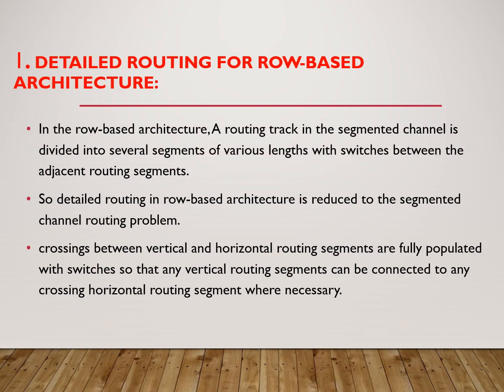Here we are going to see the detailed routing for row-based architecture. Then we are going to see the symmetrical-based architecture. See, in the row-based architecture routing, the total routing track is divided into a number of segments, right? So the routing track in the channel is divided into several segments of various lengths, with switches between the adjacent routing segments.